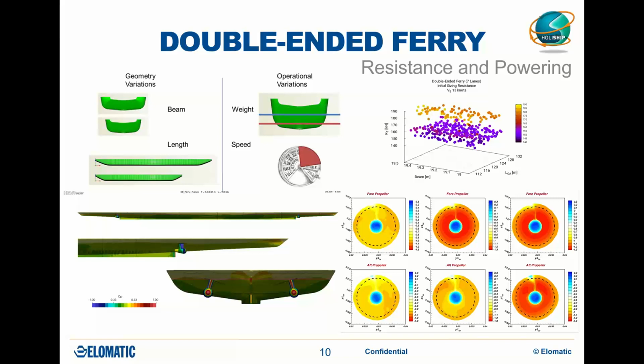But anyway, the number of pod propellers was decided based on the hull shape and the Finnish ice class regulations, which recommended the use of 4 pods instead of 2, since otherwise the power demand would have been unnecessarily high if only using 2 pods.